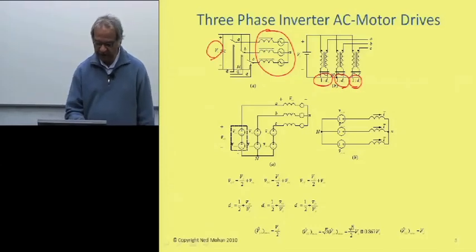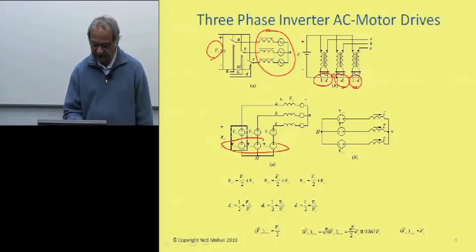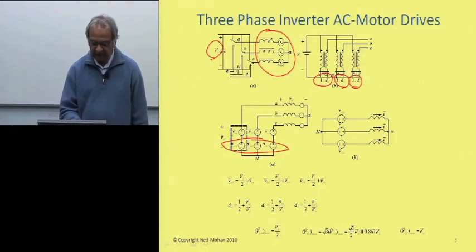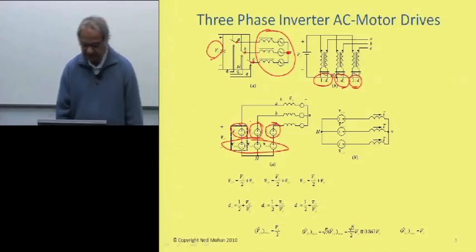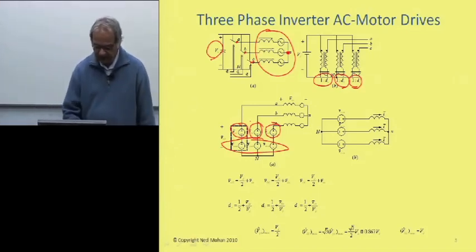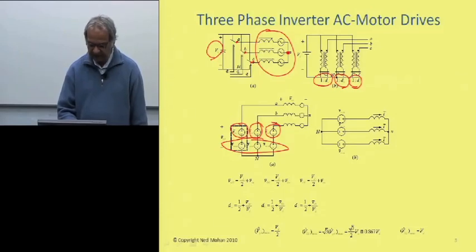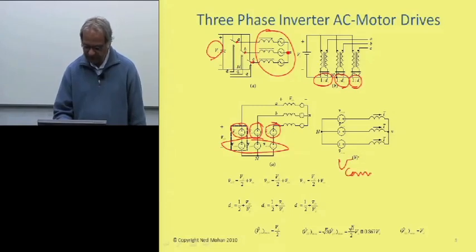So we have this common mode voltage shown over here, and then on top of that, we have what we are trying to synthesize between A and the neutral of this machine, which is VAN. Similarly, between here and this, there's this, and between this and this, what we are trying to synthesize is this. Okay, so those are listed over here, and with this common mode voltage, once again, one of the choices is to use V common mode equal to Vd over 2.